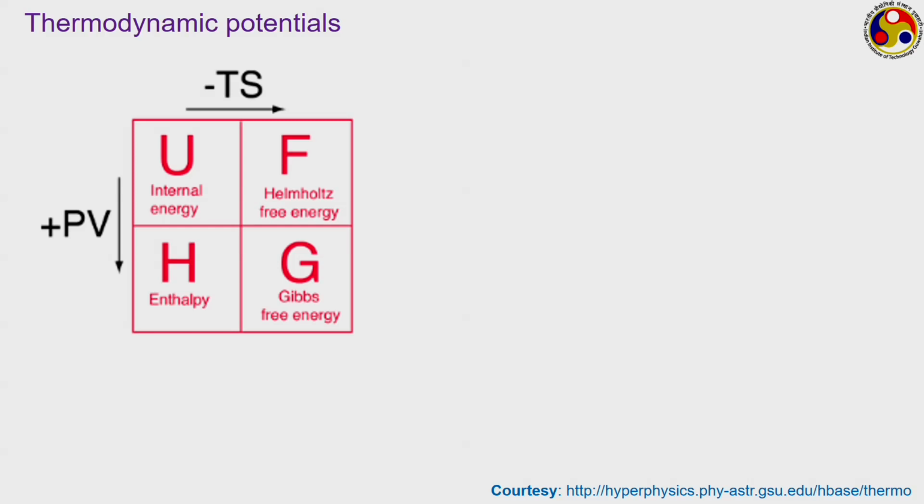Then what is enthalpy? We know to get enthalpy we have to add this PV with this U. If we write in intensive sense, then we know that h is equal to u plus P into specific volume. So with internal energy we have to add this flow work, and this flow work can be visualized as the work which you need to make some space for this particular system. So enthalpy is representative of the amount of energy needed to create the system plus the amount of energy required to make some space for the system. This is enthalpy. Then what about this capital F?